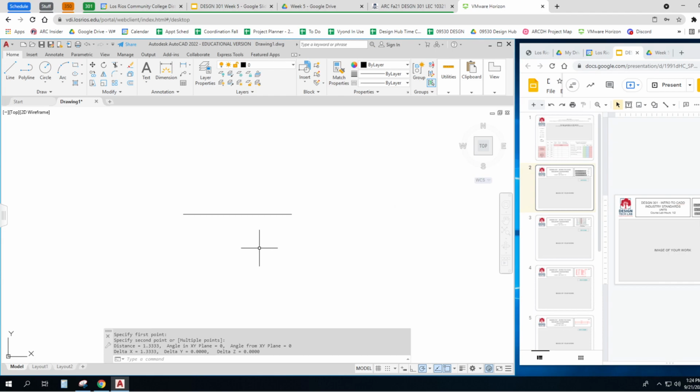So there's that first one. And so when you start working on a drawing, that's the very first thing you check. What standards are being used and what are the units that the drawing author intended to use? And if you want to use something different, you need to change it. Okay? So that's drawing standards there.